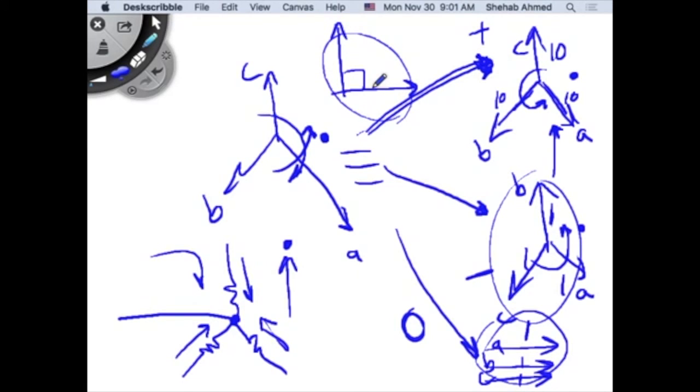You had a single supply, but this capacitor is phase shifting the voltage by 90 degrees and applying it to a second phase. When you do that, you have two phase voltages that are 90 degrees apart. When they rotate, they generate a rotating MMF. But now I have three in-phase voltage supplies that are not going to create a rotating MMF, but they're going to create current in the motor.